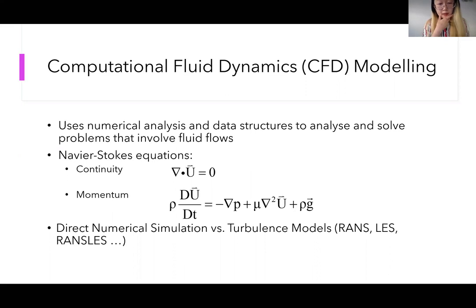And as you can see, it's pretty difficult because the Navier-Stokes equations are nonlinear partial differential equations, and it requires a large computer power. So with the computer power that we have nowadays, doing direct numerical simulation, or DNS, it is only possible to resolve the flow to a Reynolds number up to 10 to the 5, I think, and that is in nature a very not turbulent flow. So most of the flows in nature have a Reynolds number of 10 to the 5 or higher. So another alternative is to solve it using models and approximations.